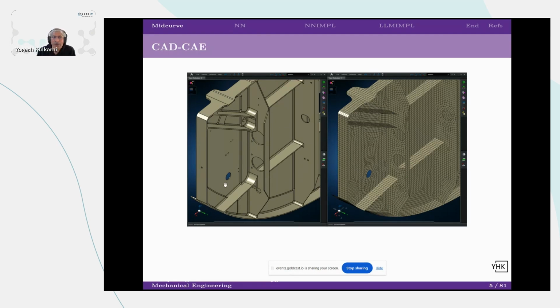All right. What happens when you are designing a shape like this? While doing analysis, you do what is called meshing, meaning the whole shape is broken into small bricks called elements. Okay. And then load is applied. And then analysis, engineering calculation, is done. Whether at this point it will buckle, it will break, it will tear off. All these things are done while doing meshing, on a per element basis. And that's how we test a shape like this on the left hand side, whether it will survive the load conditions in the practical situation. Okay, so this is meshing.